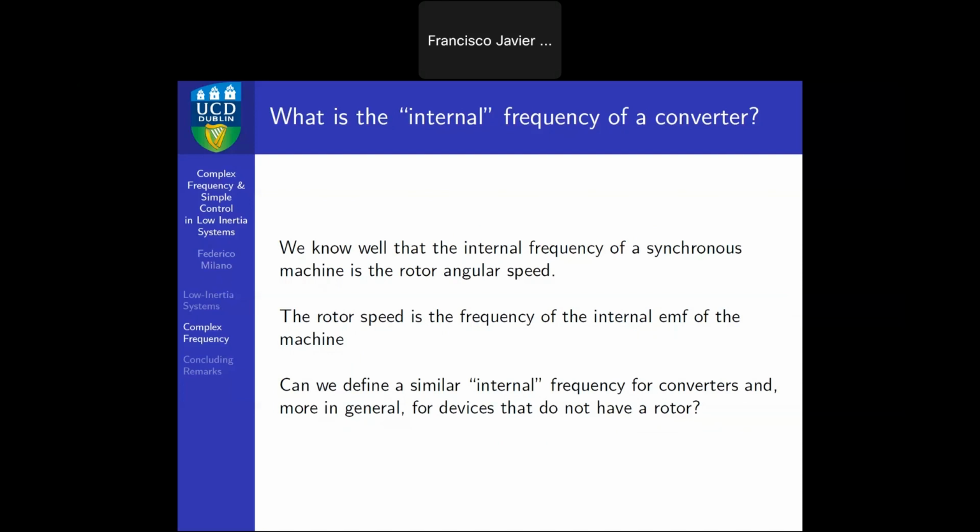In fact, not just synchronous machines. Why not? So the same way that we have the classical model for synchronous machines, where we have an EMF behind the reactance with a delta that is basically the angle, when you derive it, you have the omega. Okay? Can we do a similar model for converters and take into account the control that they have, put in the right equations to write that, say, classical model for converters?